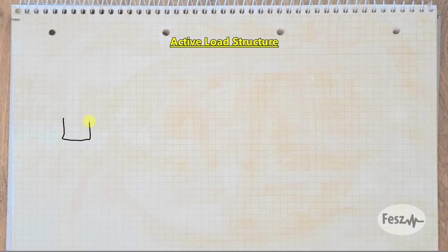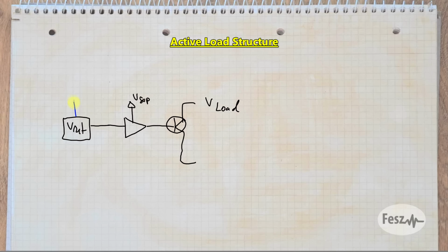So first off, the simulations use three supplies: the reference, the IC supply, and the load. While in some cases you want an external signal to make the active load variable, if you just want a static parameter, the first simplification that can be done is to take the reference voltage out of the supply. Usually the supply is stable enough to act as a reference. Maybe just a resistor divider can be added.